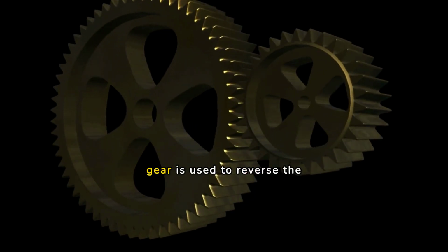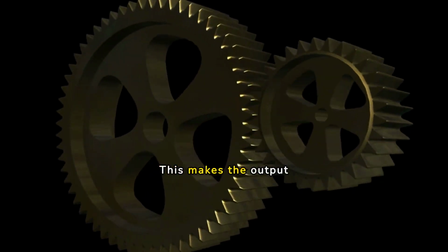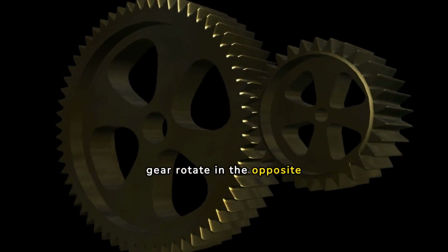The idler gear is used to reverse the direction of the output shaft. When engaged, it is placed between the counter gear and output gear. This makes the output gear rotate in the opposite direction.